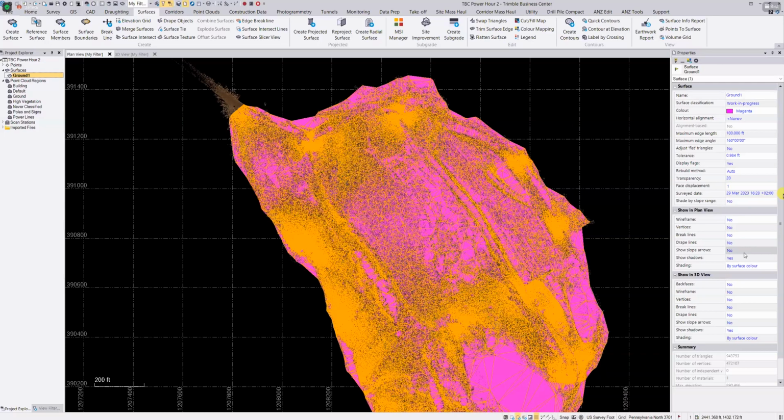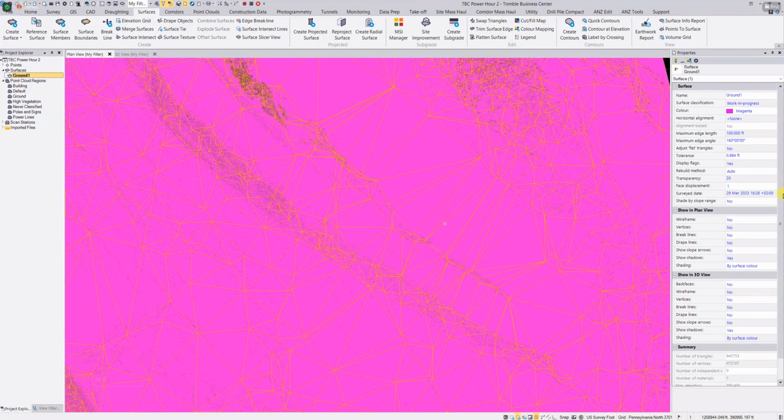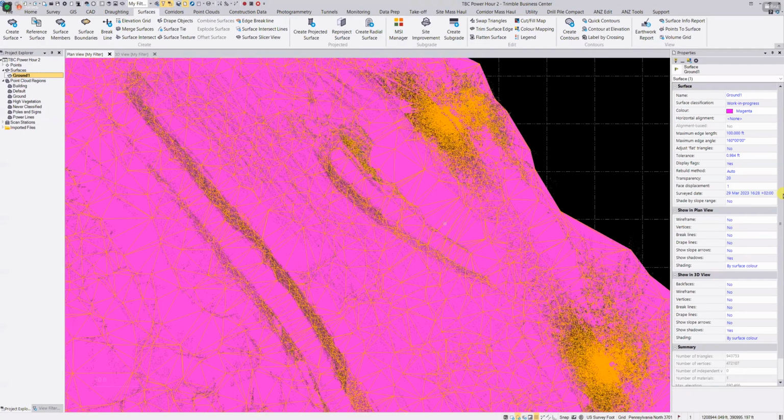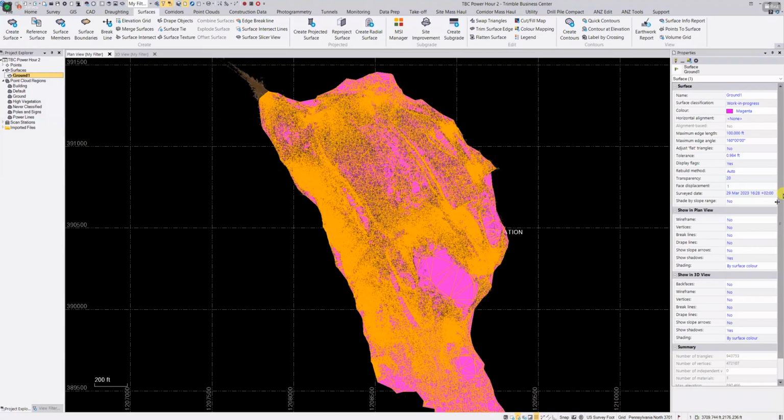View we did sort out. I just want to quickly see. The last one was just the maximum angle, edge angle. So it's just the angle of what's the smallest angle of your triangle. So you can manipulate the triangles that way by changing that maximum angle to be a little bit bigger or smaller, to ensure that you don't have too narrow a triangle when generating any of the surfaces. If you think of that angle on the inside of the triangle, that's another way that you can manipulate your surface to ensure that you don't get unnecessary or unwanted triangles in your surface.